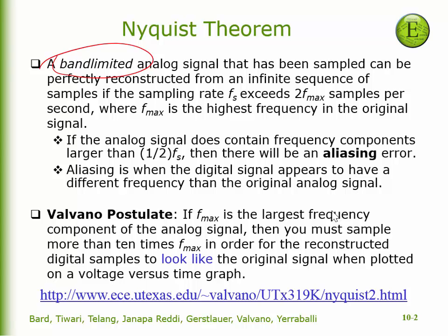So we bandpass filter it down to 20 kilohertz. We give it about an extra 2 kilohertz for the filter to roll off. And anything that's there is going to be played back.